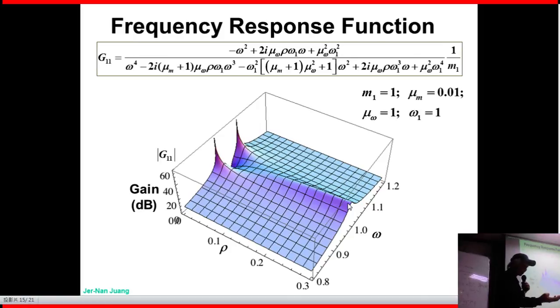Do you like a quicker damped, or over damped, or under damped? But the same happens here. Okay, so from this part, what kind of damping ratio do you think you want? Of course, you want to be somewhere like this, there, right? Or somewhere like there. So that's being less than 10%. All right, so from this very simple frequency response function 3D plot, you will be able to design the damping ratio for your system.